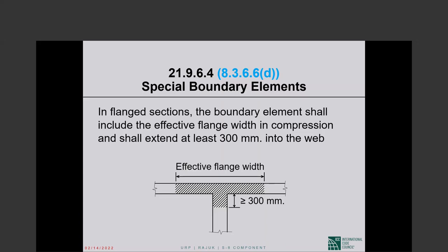At the very top, if the shear wall is discontinued, do you build a beam at the top? That may happen. That depends on what you are trying to do and what the rest of your framing is. But this is the best answer I can give you: along the height of the wall at the different floor levels, you never try to build a beam inside the shear wall.